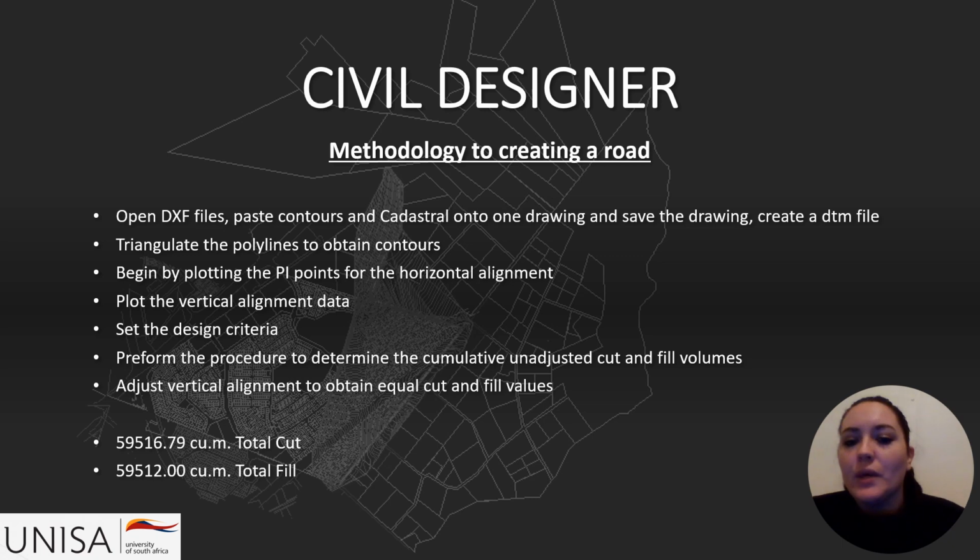So instead of following a gentle slope, which is what I used, the road would need to follow more on the natural ground level instead of the design level. So my slope was more gentle. We would need to increase the slope so that it follows the ground level. Although this area is quite steep, it would be up to the designer or developer to decide, do they require a gentle gradient or would they use steeper slopes for the road.